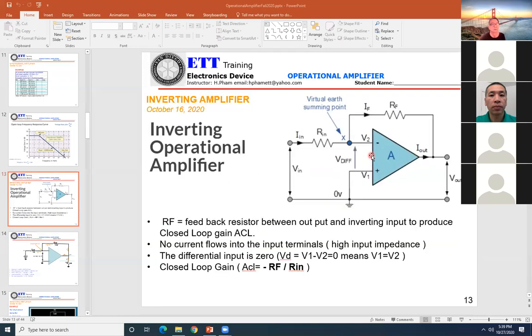Mr. Pham, for that example, there is only 0 volts in, only for that example, 0 volts in. 0 here? No, to the left. Here? Yeah, right there. So there 0 volts are going in right now instead of... No. They just gave V in, they did not give you the value. It's not 0 V in. There's a voltage going in, but once you go through the resistor, the voltage drops to 0 at point X. Right. That's the potential drop.